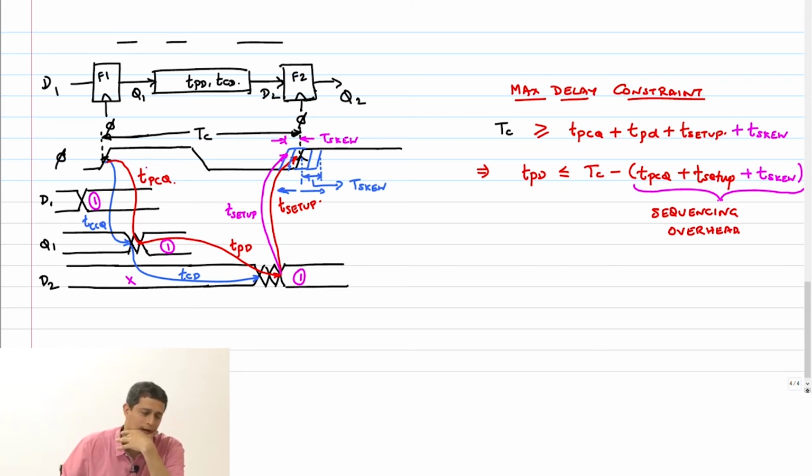Between any two clocks, right? Therefore if I consider T skew here once, I'm done, because I've considered between any two random clocks, this is the maximum number. So you could divide it as T skew by 2 here, T skew by 2 there, doesn't matter. But it's just one counting. So what he's saying is the T skew definition is the worst case difference between any two clocks on the leaf nodes. That's what is T skew. Okay, so that we have taken care of.